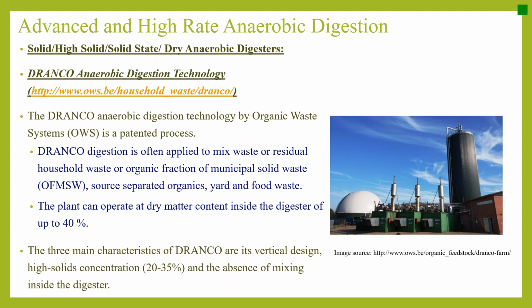Dranco anaerobic digestion technology. The Dranco anaerobic digestion technology by Organic Waste Systems is a patented process as well. Dranco digestion is often applied to mixed waste or residential household waste or organic fraction of municipal solid waste, source separated organics, yard and food waste. The plant can operate at dry matter content inside the digester of up to 40%.